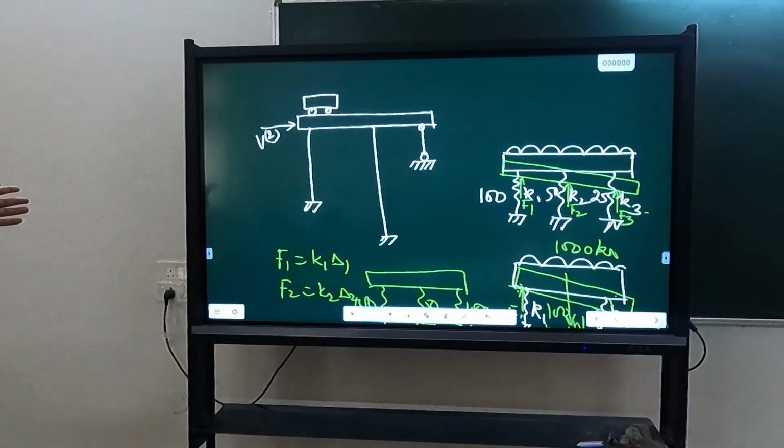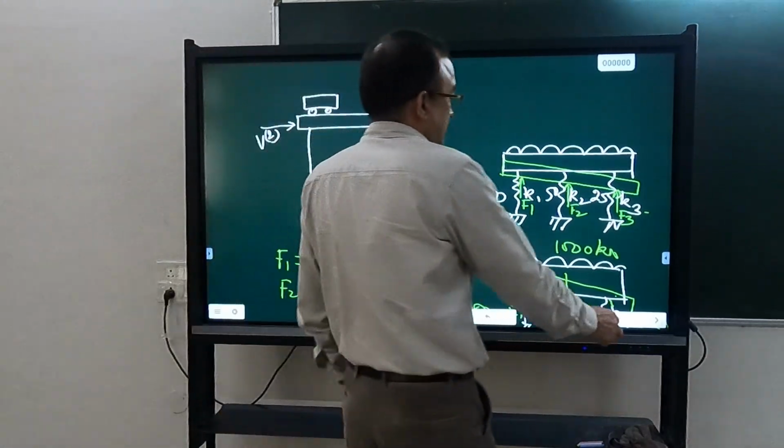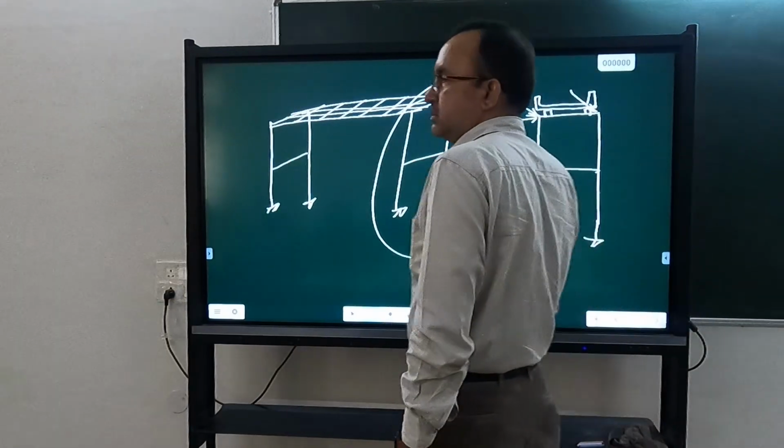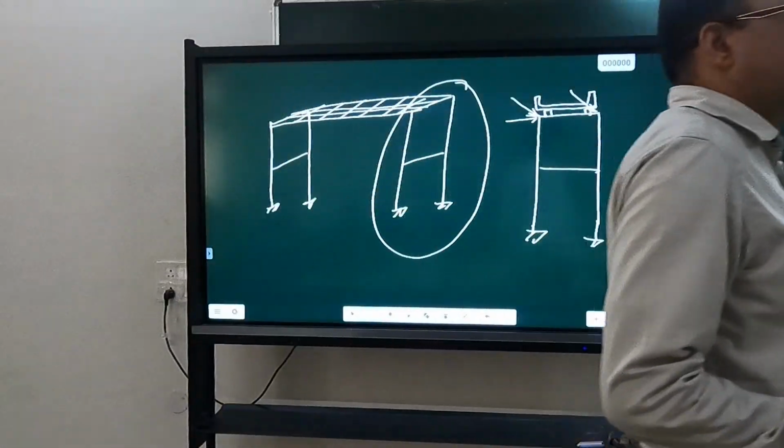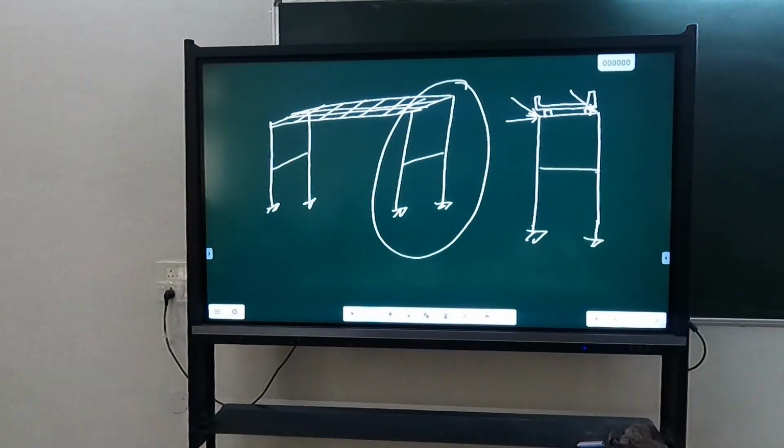Are these determinate structures which I have plotted here? This one is not. It is in the transverse direction. Okay. What about this one? Is it determinate structure? It is determinate, it's straight, in longitudinal direction. Okay. So in most of the cases, not all bridges, suppose you have an integral bridge with multiple columns, then it is not determinate in any direction.